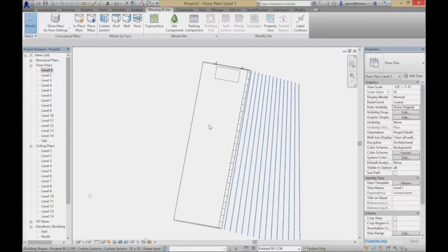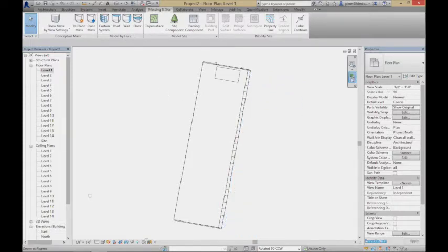So whether this building is going to take 2 stairs or 3 stairs, I don't know. We'd have to look at the length and the rules. But I do know it'll take at least 2. Because in a big commercial-like building like this, if it has over a certain number of occupants, we always have to provide at least 2 exit routes, just to allow that if on one end of the building there was a fire or some sort of blockage, there'd be an alternate route. Okay, so that's more of an architectural issue.